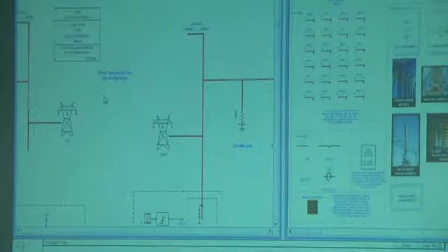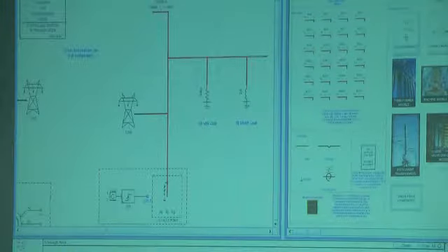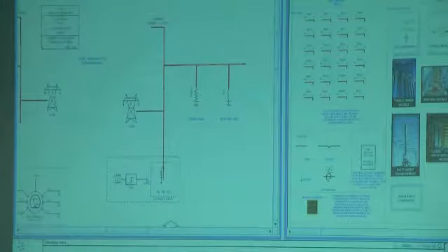So if the time step is 50 microseconds, and we assume the speed of light for travel on the transmission line, we wind up with about 15 kilometers. So if we use chapter 2 here, this line is default 50, so that should be enough to split. So in this case, we don't need to split. It's very simple, but I'm just showing you how we can do it.